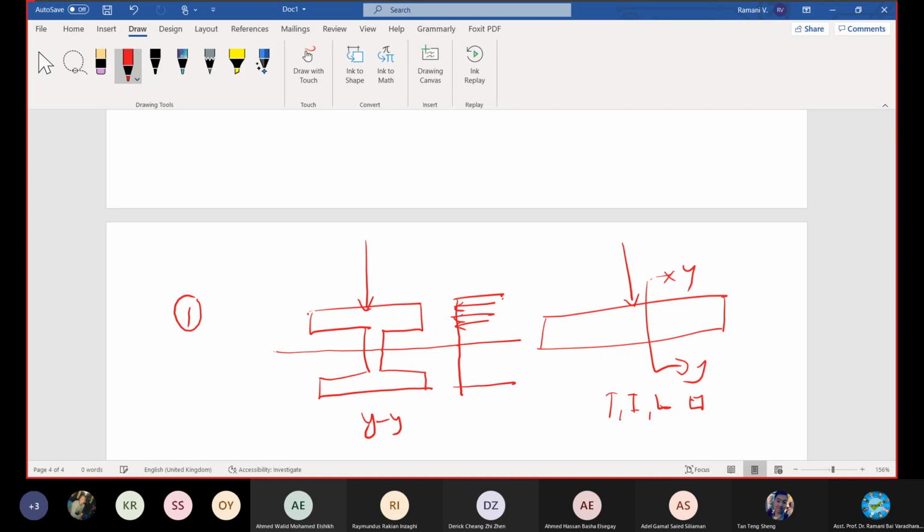So the compression is going inward, just put it like this. Is it reducing towards the neutral axis or not? Neutral axis, AB. Will it be reducing towards the neutral axis or increasing towards it? Compression. Increasing or reducing? It will be reducing to 0 at the neutral axis. And then the loading is happening here.